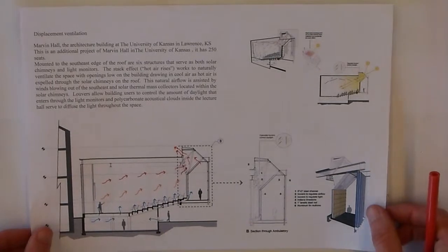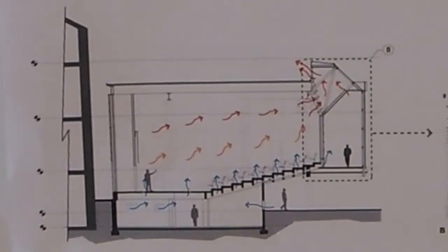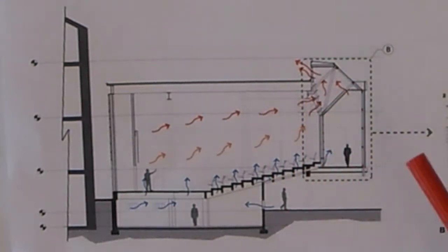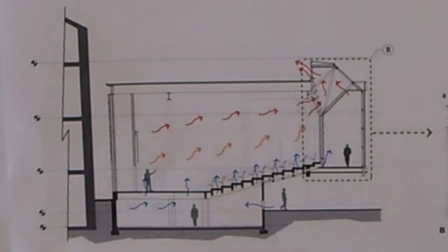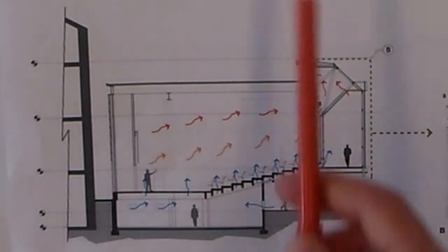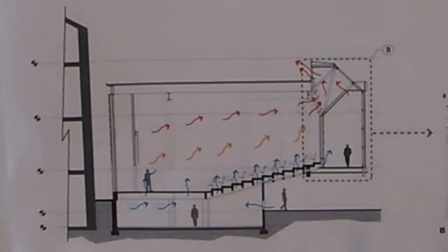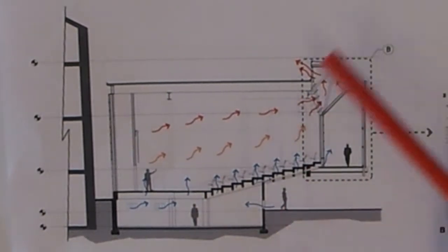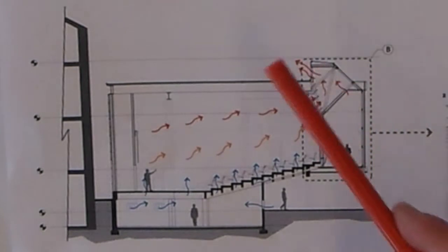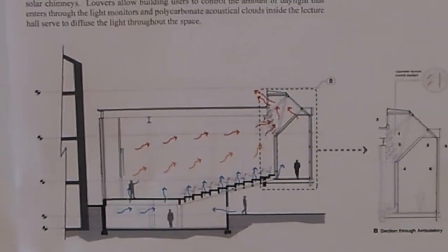Continuing with the design directions, we are using the concept of an air chimney. This creates heat buildup over here. Because the hot air is attracted, an airflow is created. This also causes underpressure in the lower area of the room, which creates an airflow from fresh outside air through the room to the ceiling.